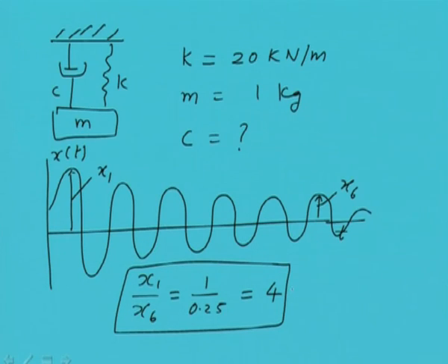So you can see how through measurement we can get the damping coefficient if we know the system property, mass and the stiffness of the spring. So we have seen some of the analysis of the damped vibration, especially using the viscous damping. And as I already mentioned earlier, there are several other kinds of damping, and their mathematical models are quite complex. Also, the analysis for free vibration is not simple for these cases. So people have developed equivalent damping models that we'll be seeing in subsequent lectures.